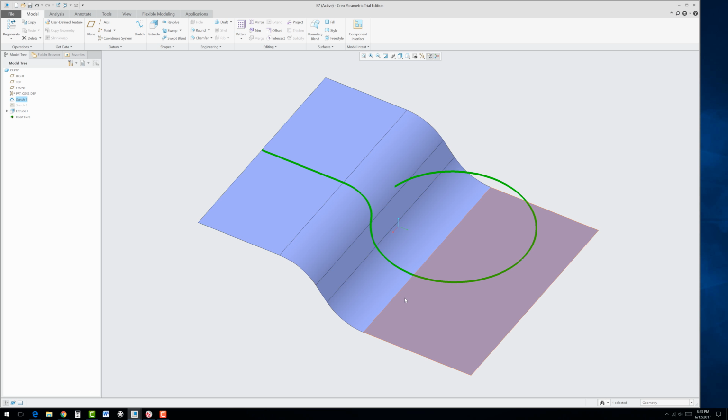And once they're all selected, now you could go to the chain, select the wire that you created, and the direction reference. Go ahead and click in there and select this flat surface up here and flip the arrow so it's pointing down.